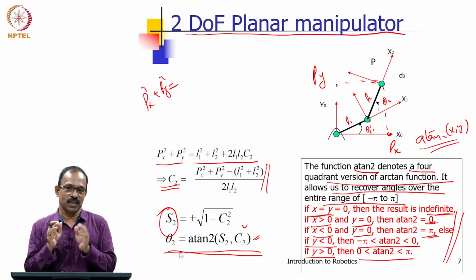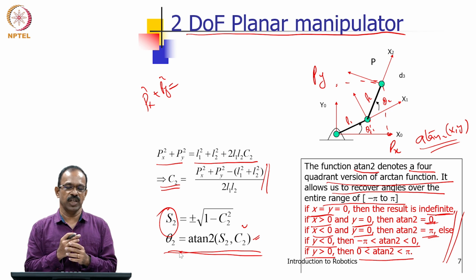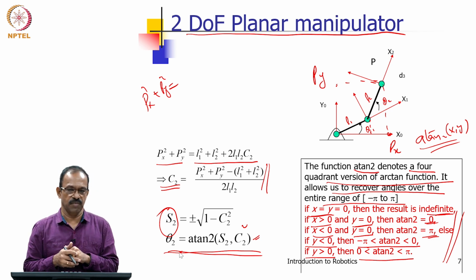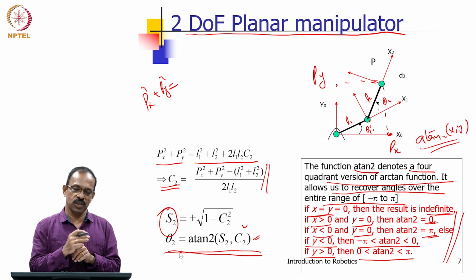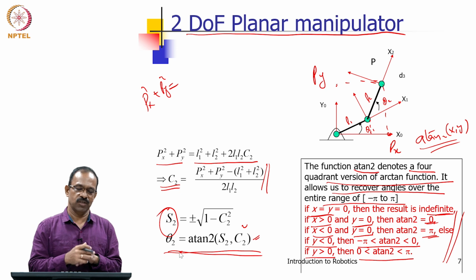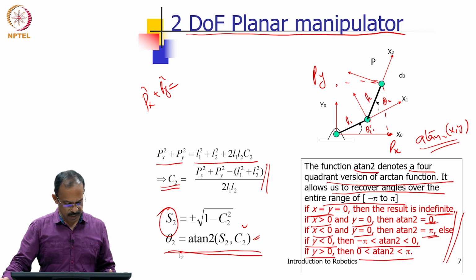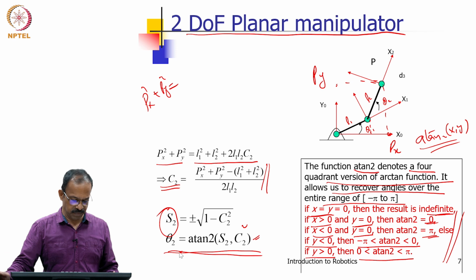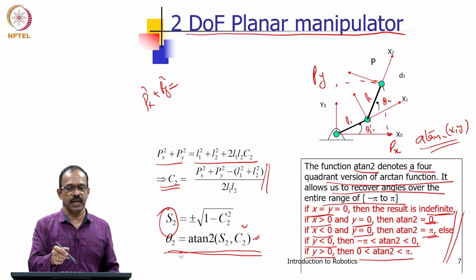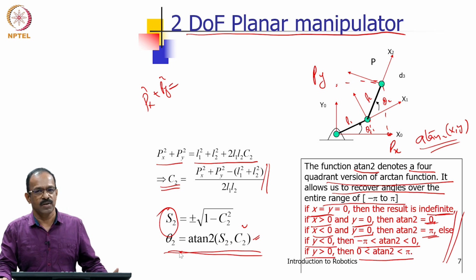But if both happen to be within the joint limits, that shows there can be 2 ways for theta 1 and theta 2 in this case, and you have to use both values for solving the next joint angle. So, you will be getting multiple solutions that way. That is how you get theta 2. Now, you need to solve for theta 1. You have to substitute for Px, Px equals L1 C1 plus L2 C12, that relationship, and solve it for the next joint angle.